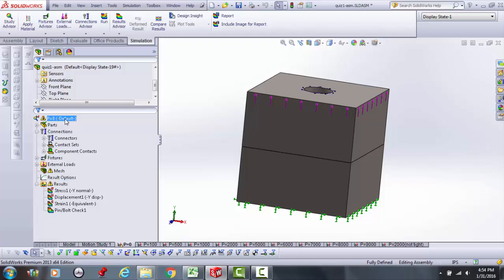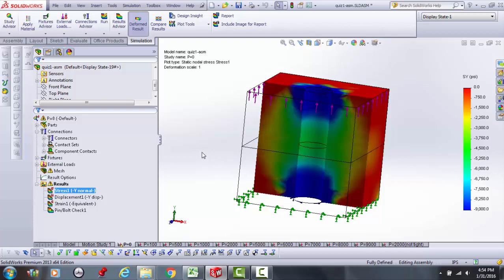You've got the same meshing options you can go find. I just left it as standard for now. And then you can go look at the stresses, and I've set it up for Y stress. I've taken a cut in the midplane so that you could see what it looks like, the truncated frustra here, and the blue showing that it's really in compression where the bolt head is and where the nut is, and then it's less compressive as you taper out. So that's looking kind of like we expected.